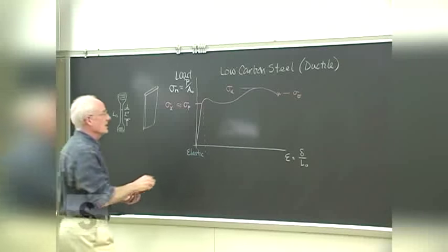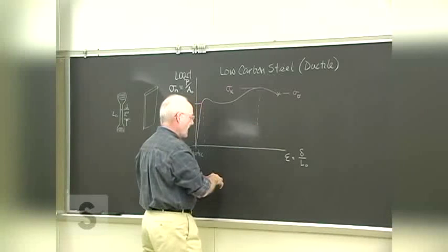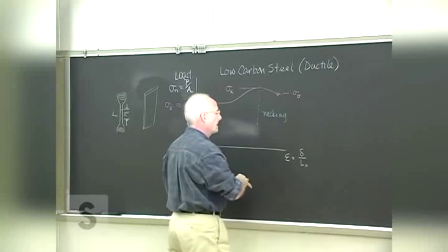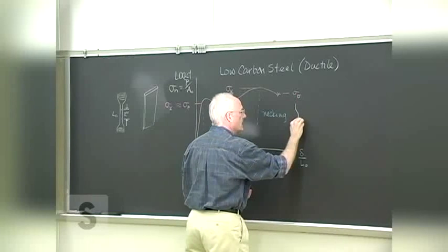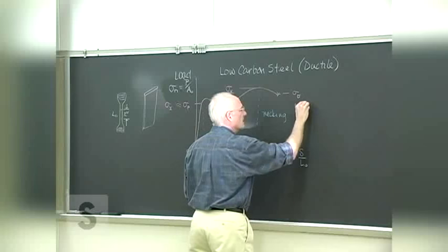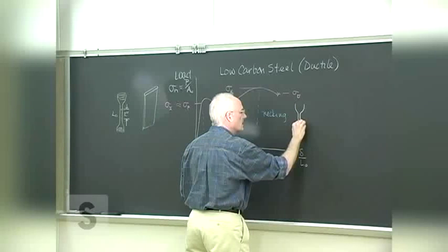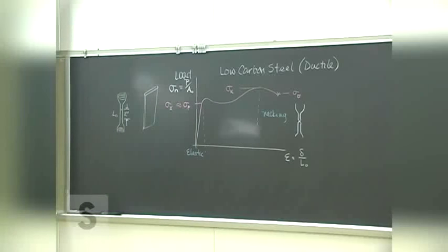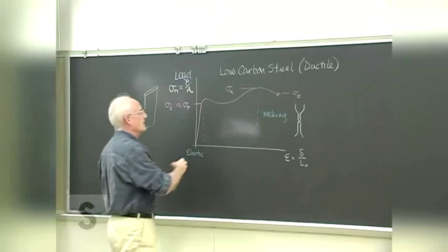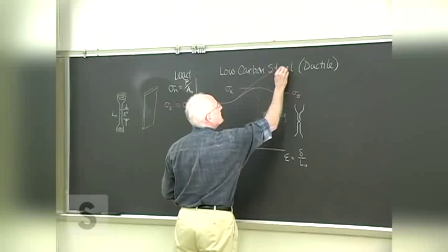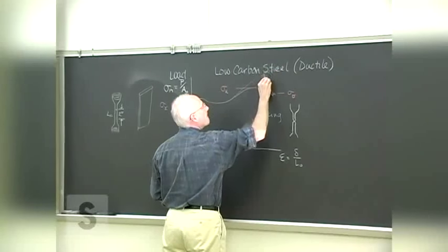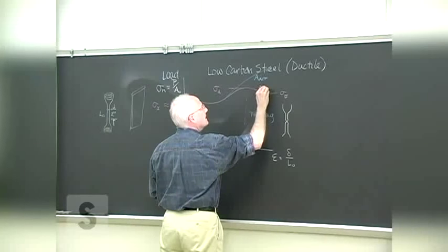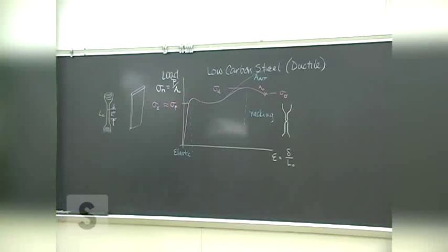This is well into the region where that necking occurs, where the narrowing down of the material in the test section itself causes a drastic reduction in the area that's withstanding that stress, and the real curve actually goes something like this if you use the actual cross-sectional area as opposed to using the original or nominal cross-sectional area there.